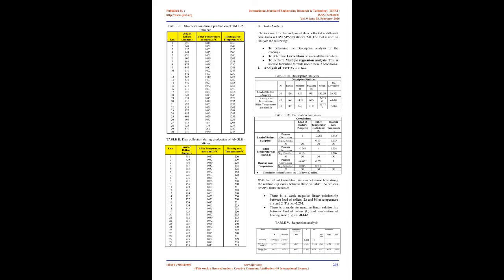These problems arise due to failure of the lubrication system in rolling stands, the cooling system in stands, electric failure, uneven temperature of billets, mechanical problems, high rolling speed, etc. This problem impacts production qualitatively as well as quantitatively: loss of human effort, raw material wastage, and breakdown of the mill. Furthermore, it takes a lot of time to start rolling again and hence causes high production loss.